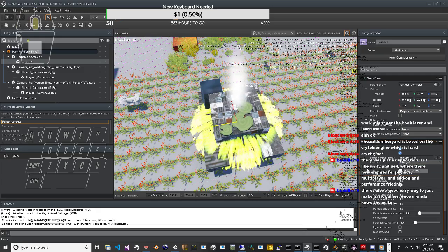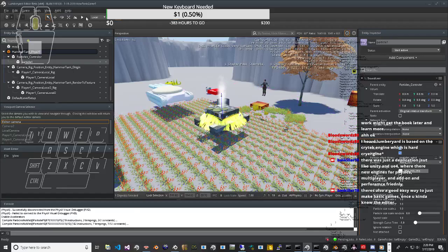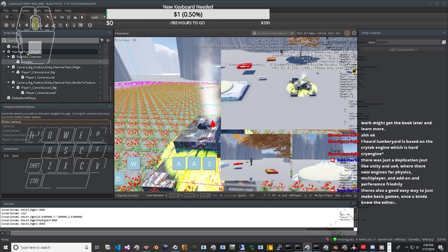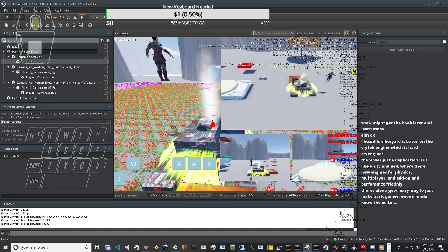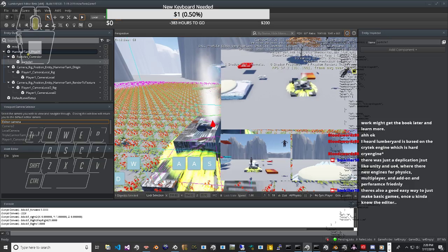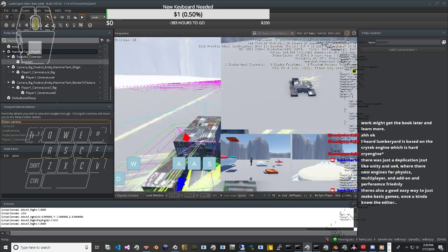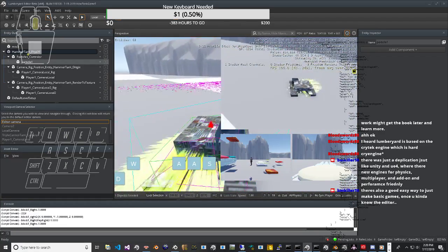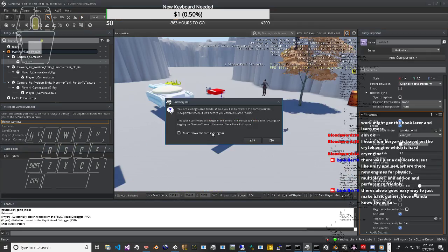Also notice that the generated force peaks at around S equals 0.08, or 8%. The peak would be something one could definitely feel in the driver's seat. Overcooking the throttle or brakes would produce a palpable reduction in G-forces as the tires start letting go. Worse than that, increasing braking or throttle beyond the peak leads to reduced grip. This is an instability area, where increasing slip leads to decreasing grip. Finally, note that the function behaves roughly linearly with Fz, showing that it acts like a Newtonian coefficient of friction, albeit a different one for each value of slip.